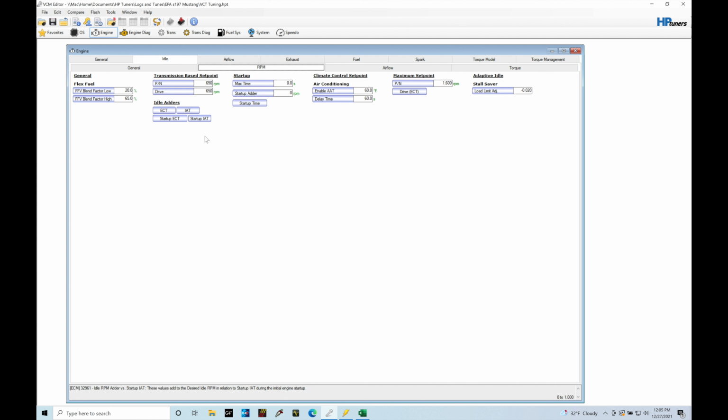Depending on the size of the throttle body and a lot of factors within the drive-by-wire control, we'll find that a very small amount of throttle plate movement leads to a relatively large change in airflow at idle conditions. Large airflow changes can lead to large torque changes, which can really have an influence and a jump on our desired engine RPM.